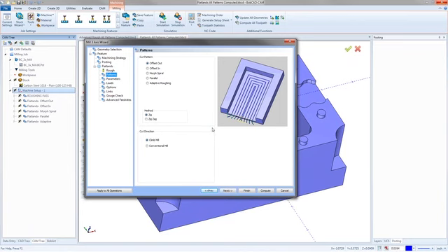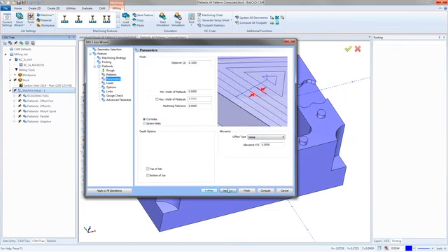So same kind of thing with the patterns as the advanced rough, because the flatlands really are part of the advanced rough. It's the reason we have the flatlands toolpath. So you've got the offset out, which starts on the inside and works its way out, the offset in, the morph spiral, the parallel, and the adaptive roughing. Right, here are our parameters. I would always try to go with like a 50% step over if the tool can handle that. In this case, I will.